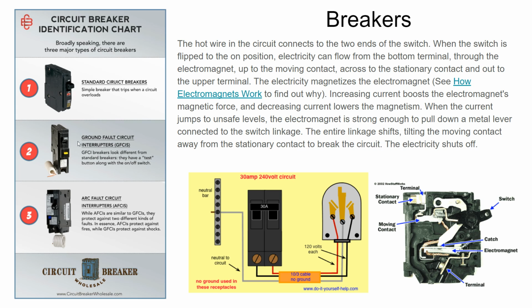We then also have arc fault and ground fault interrupt. That is for more sensitive stuff, essentially. Or if something could potentially get wet and cause a short circuit. Those two are, as I said, specifically for instances where you want to have additional protection on those circuits. There are also regulations which I'm not super familiar with. I'm working on becoming more familiar with it, but there are different codes now that govern where and when those should be used, and they're being used more frequently.